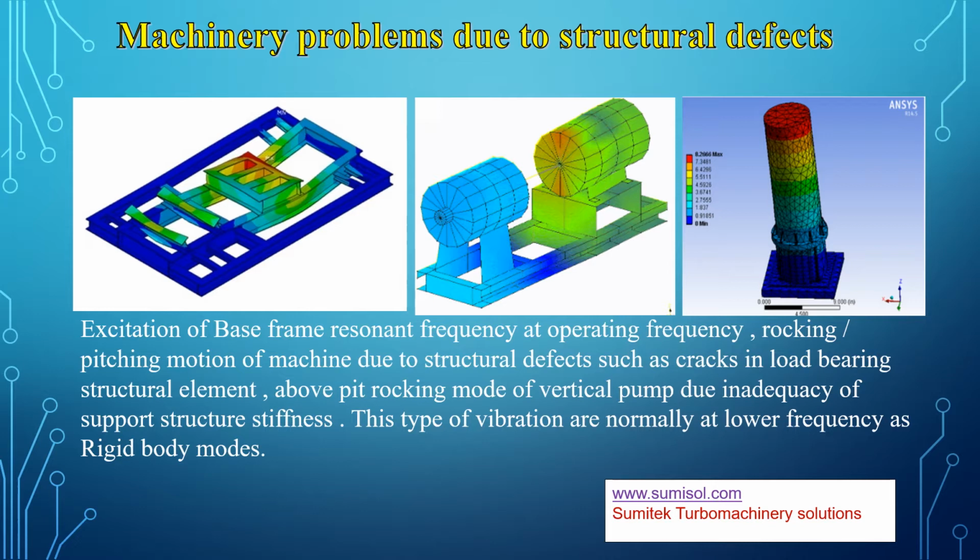It is fairly difficult to identify these anomalies, mostly because the recent methods of identification are not only expensive but at the same time fairly cumbersome. For instance, the current technology asks for operating deflection shape analysis or ODS, or an experimental modal analysis using FEA tools, and sometimes even demands the use of high-speed motion amplification cameras to try and better understand these structural defects.